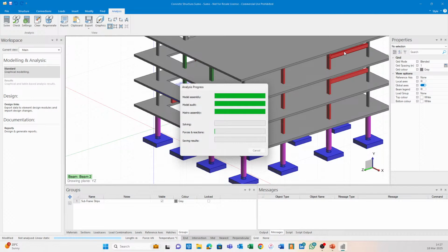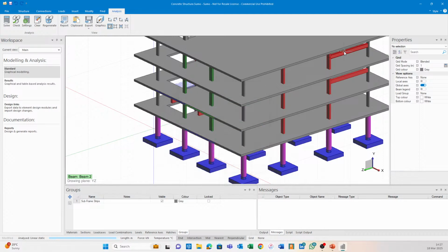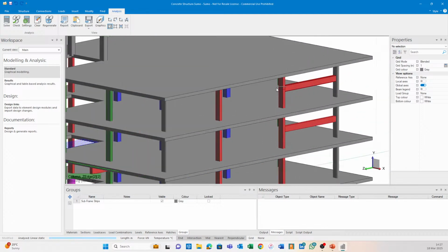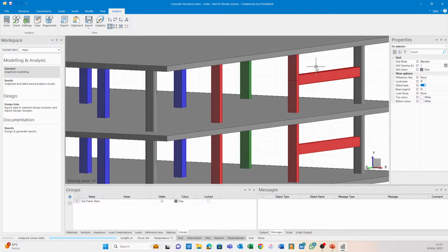The same can happen if you have a line load that doesn't run over the full length of the column. If anything splits the column with nodes, which loads can, you're going to have a problem. So wherever you have anything coming in laterally, or anything that splits the column into more nodes or more segments, you have to split that column physically like this.